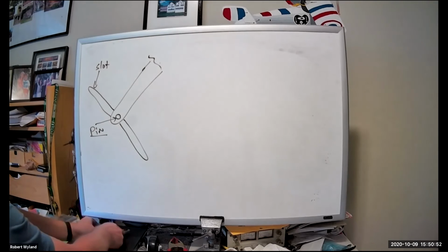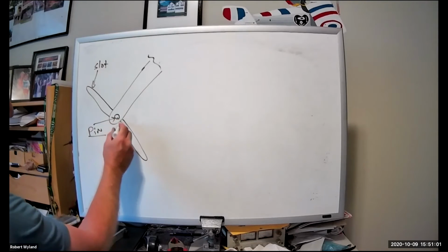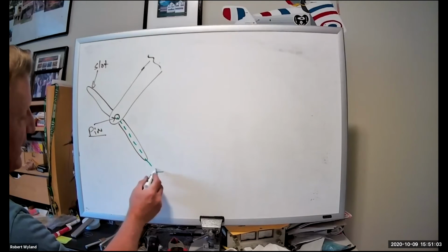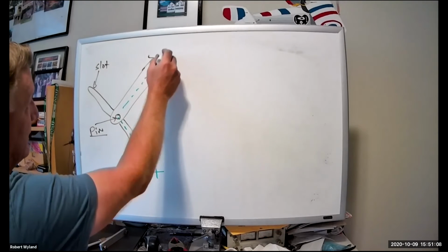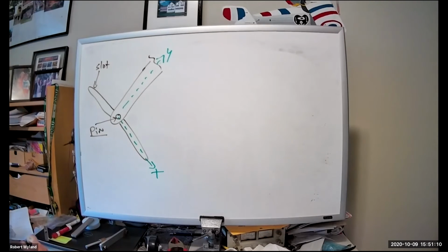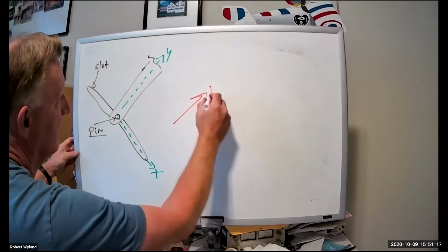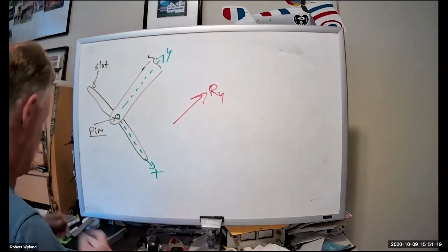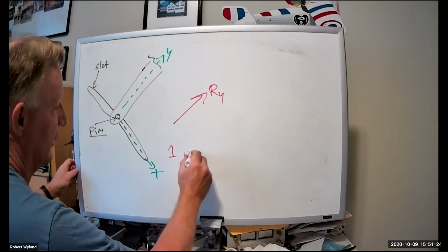So it's really the same identical situation as the one above, the collar with a smooth pin. So we do the same thing. Make this X. Make that Y. And the only reaction we're going to get right there is going to be RY. So we have one unknown.